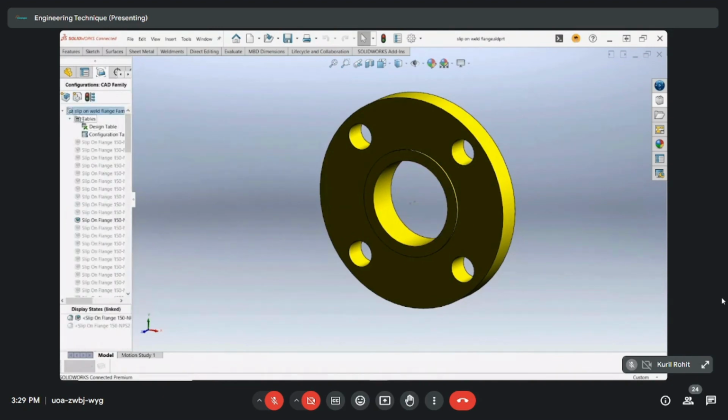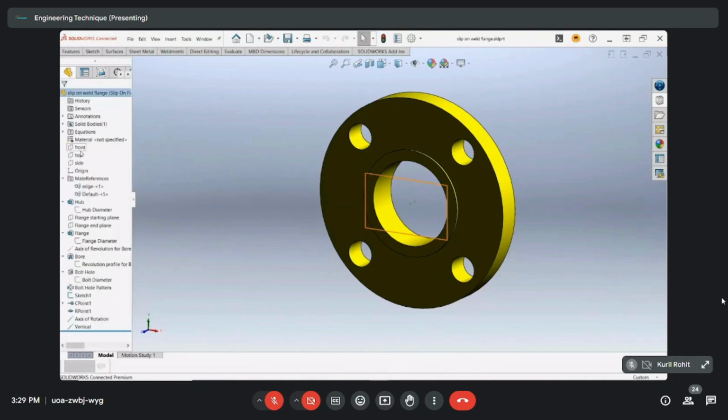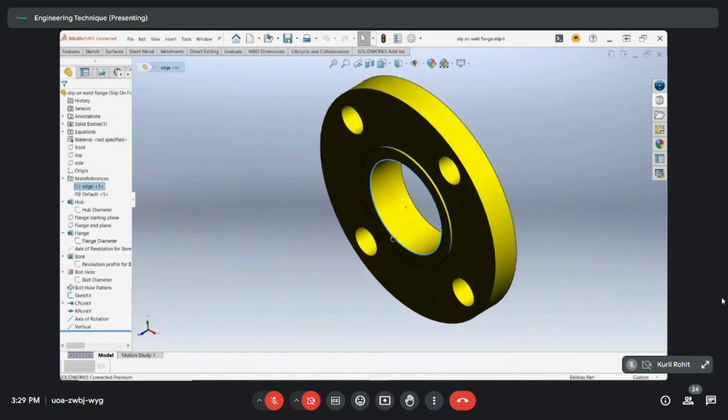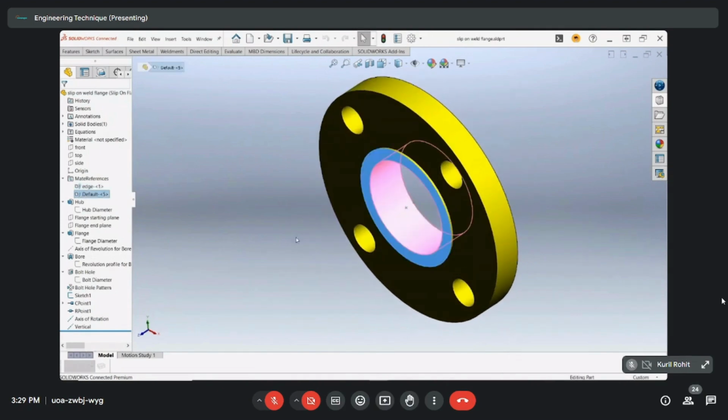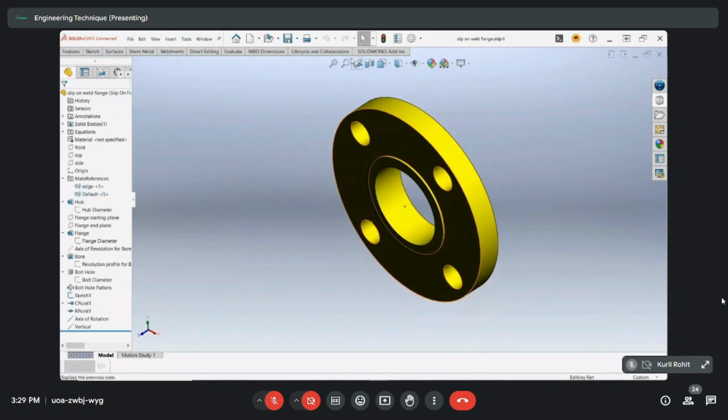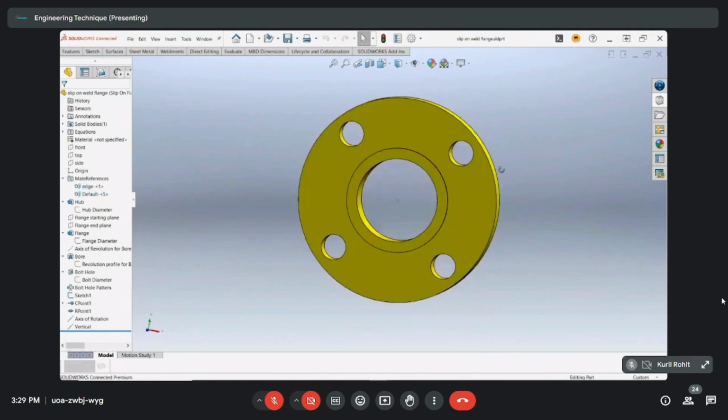That is why utilizing a pre-existing component is mandatory while creating your custom part. It will help you through everything. You can see the edge is added, the mate references for planes are added. So this is the best option, that we should utilize our predefined and pre-existing design library components for our custom library parts. You can add numerous parts utilizing those components and those settings without making much effort.